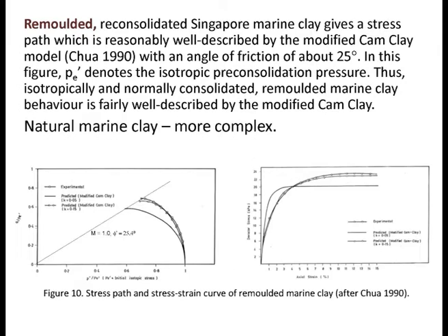Now, for Singapore marine clay, we have done quite a bit of tests, and we show that in most cases, ironically, the modified Cam-clay is not considered the most accurate model for soft clay, even for kaolin. But strangely enough, for marine clay, it seems to work quite well. For our marine clay, it seems to work quite well.